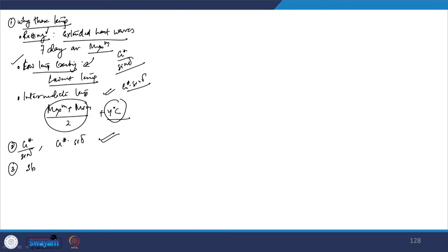Talking about the stress controlled testing. DSR for PG grading is done under a stress control mode. So, what is done here, in order to achieve the target strain range of 10 to 12% or 1%, the DSR will do an initial adjustment to the torque. It will set the stress level at which this strain can be achieved, alright, and it will maintain that stress level, and therefore this is a stress control test.